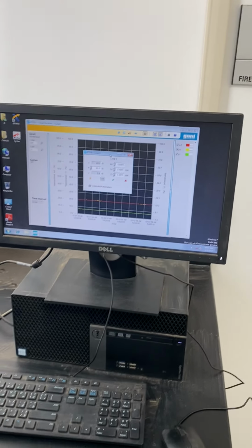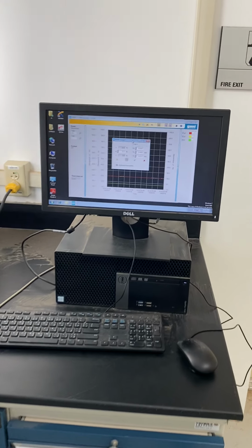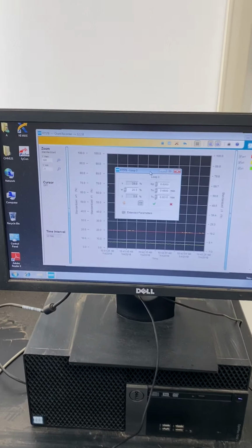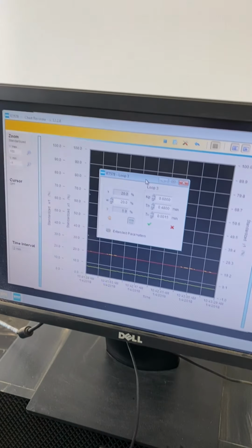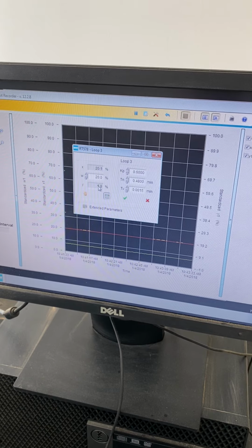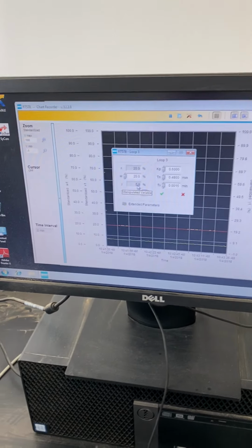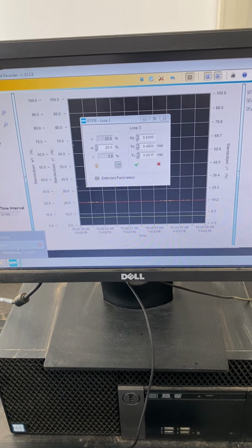The controller, whether it is the operator in manual mode or the automatic controller in auto mode, will compare the measured value with the set point, and based on the difference between the two values, it will decide what action needs to be taken, and that is in the form of sending an output signal.